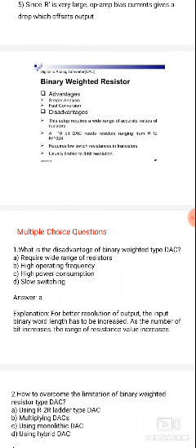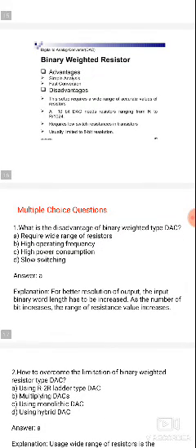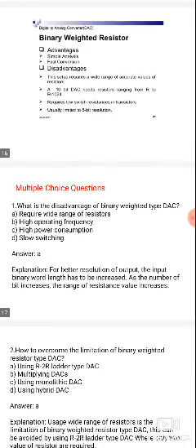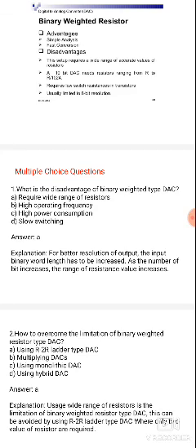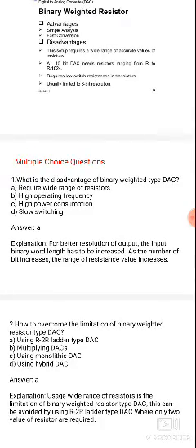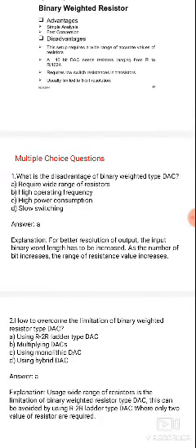Next, the binary weighted resistor DAC has a simple analysis and is a fast conversion method. The main disadvantage is that the setup requires a wide range of accurate resistor values. The complete circuit depends only on the weights of the resistors, so the resistor weight is important, and the accuracy of the resistance is also important. Weight depends on the resistors R, 2R, 4R, 8R, 16R.